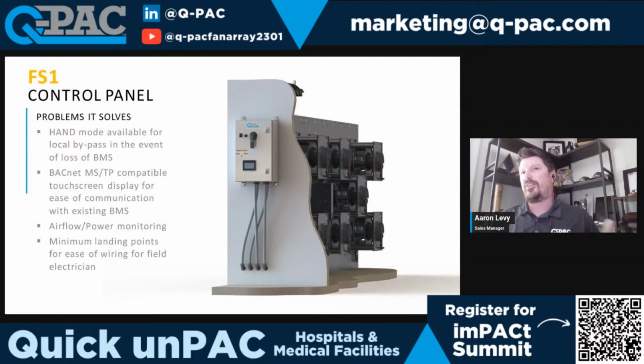What I don't like for somebody to do is turn that thing all the way up to 10, because depending on how that system is designed, you could get a very large rush of air through ductwork that may or may not be able to handle it. So I always tell somebody, to keep your system's efficiency and keep your airflow where it needs to be, to have a local reference point right next to the potentiometer.